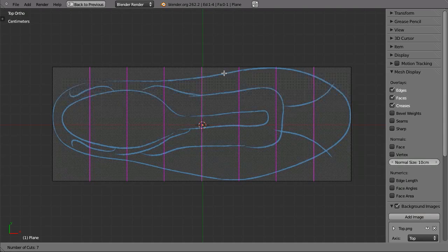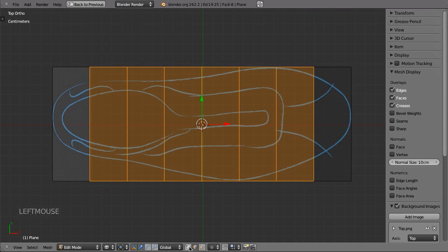Through experience and working through it, you will at one point just see when you need to add geometry. I would advise you to start with a low polygon model, because it's a lot easier to modify a low amount of vertices compared to a large amount, and you can still add more detail afterwards. So with 7 points, I feel pretty comfortable.